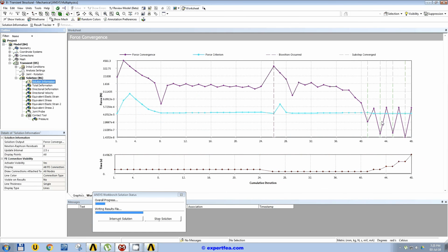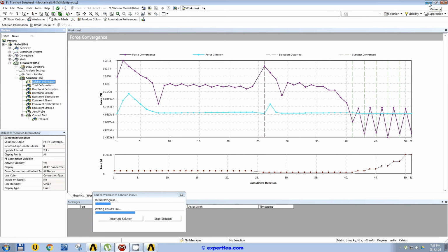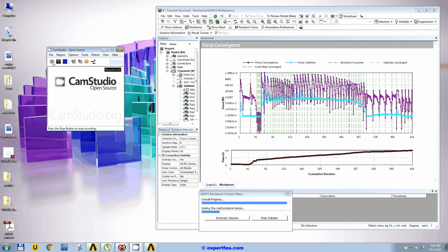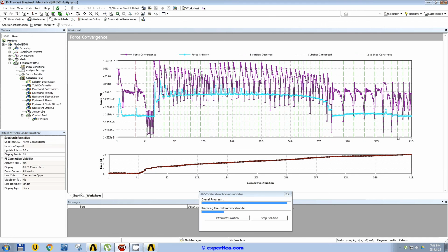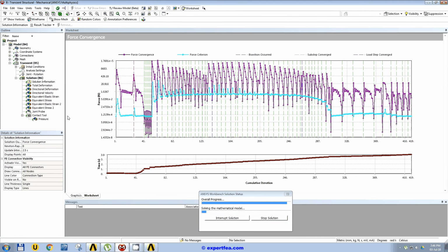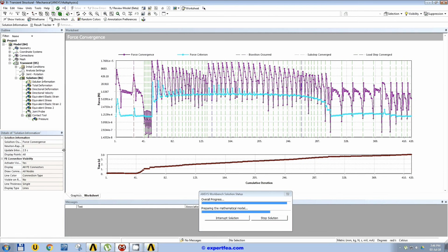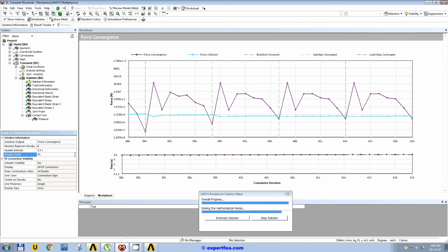Look, convergence appeared, and will return in a few seconds after the solver works more. Yes. So it seems like the FEA is converging pretty well. We're close to the end. If this view is very confusing to you, remember that you can change the display points to whatever number you want. I usually choose 35.